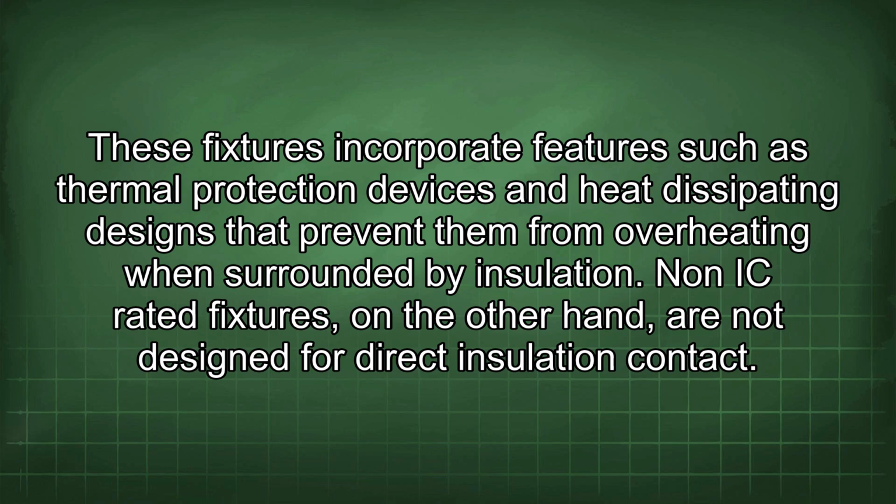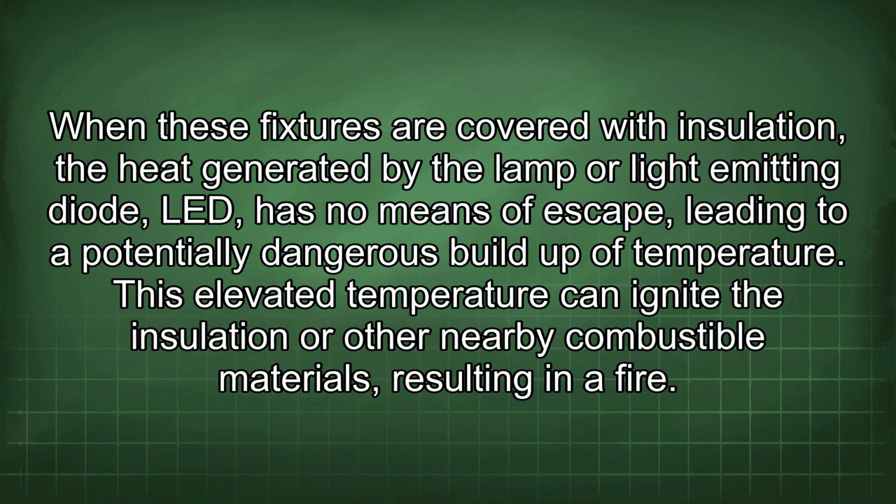Non-IC rated fixtures, on the other hand, are not designed for direct insulation contact. When these fixtures are covered with insulation, the heat generated by the lamp or light-emitting diode, LED, has no means of escape, leading to a potentially dangerous build-up of temperature. This elevated temperature can ignite the insulation or other nearby combustible materials, resulting in fire.